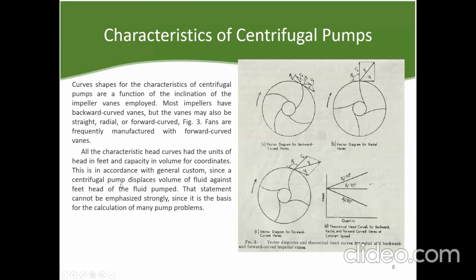For the characteristic of centrifugal pump, curves, mga curve niya, shapes for the characteristic of centrifugal pumps are a function of the inclination of the impeller vanes employed. So most impellers have backward curve vanes. Ito yung backward, ito yung quantity head, yung performance curve niya.